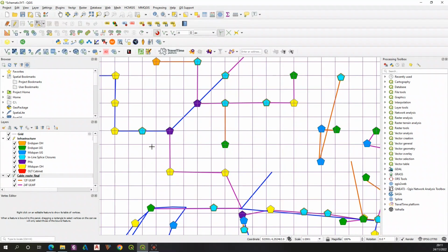There are two things we can modify in preparing the schematic, namely the snapping tolerance, which you can see is already set at 25 pixels. What does it mean? If, for example, I try to move the element from here to there now, and I would like to place another one in the vicinity, I cannot really, because it's been snapped already to the nearest line, which falls quite far from the element.